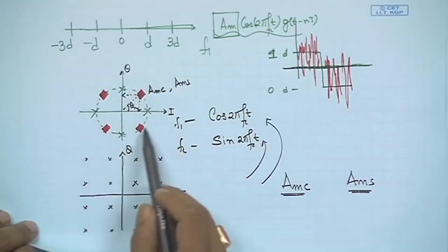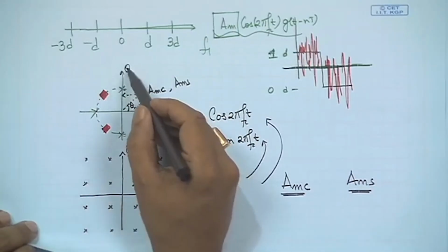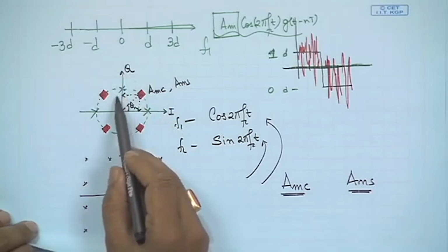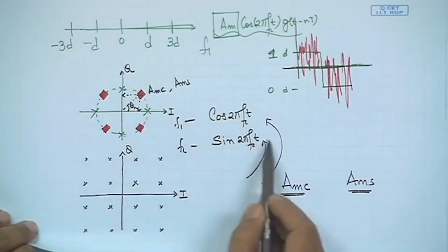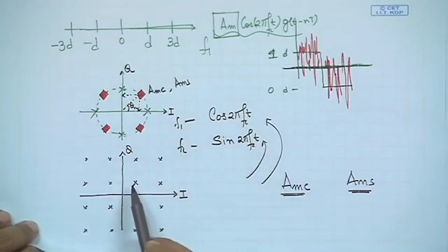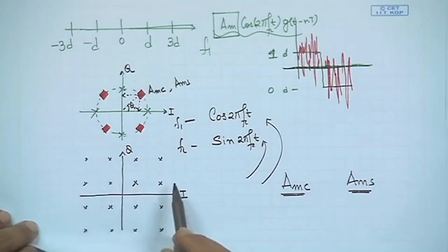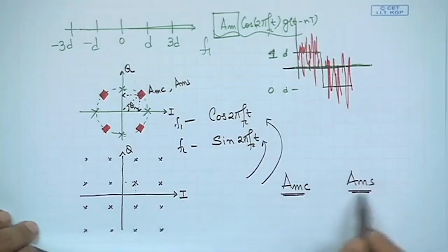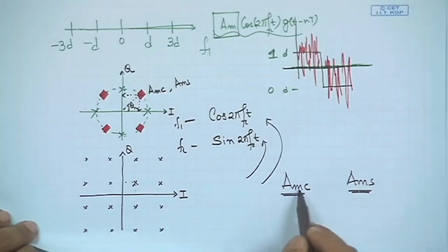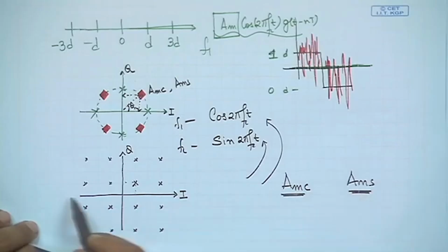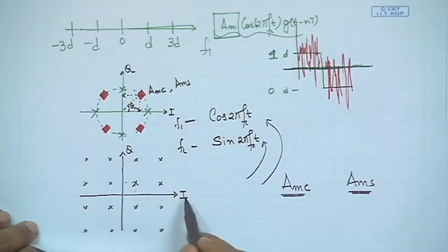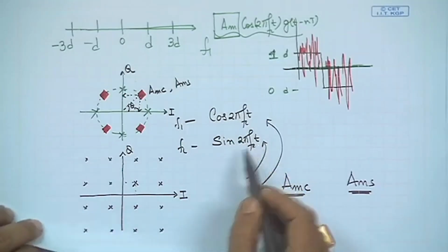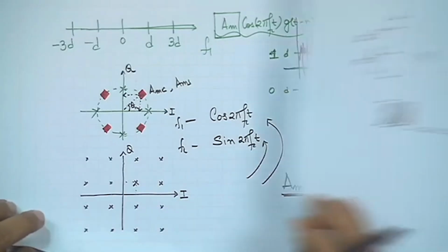For phase shift keying, we said you could decompose into an I and a Q channel, and you could have projections on the I as well as on the Q, and these are the components on one basis and the other basis. Then we moved on and discussed that there could be a QAM constellation, whereby you straight away have this relationship, that means there is an amplitude in the cosine carrier and an amplitude in the sine carrier, and it goes as quadrature amplitude modulated signals. So, in these two cases there are two basis functions, one along the I, that is this one, and one along the Q, which is this one. These are the two dimensions that we have looked at.